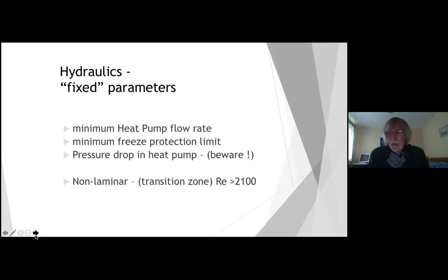Now, as a designer, you've effectively got some fixed parameters, so at least something gets bolted down for you. You've selected your heat pump, and the manufacturer will have a minimum heat pump flow rate. You might not necessarily fully agree with it, but from a designer's point of view, you probably want to take care that you are going to achieve that minimum heat pump flow rate. Because the first thing a commissioning engineer from the manufacturer might do when he turns up on site is say, you're not hitting the minimum heat pump flow rate, I'm not even going to bother. So bear that in mind, and that's a given for you.